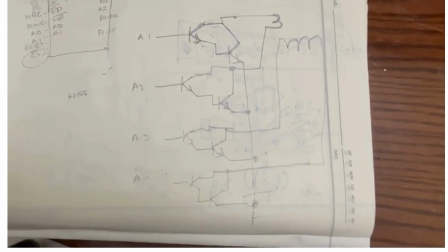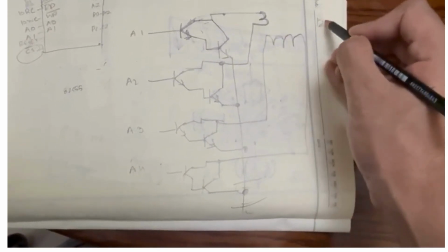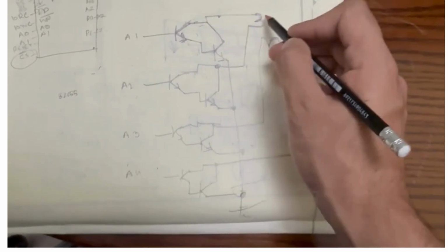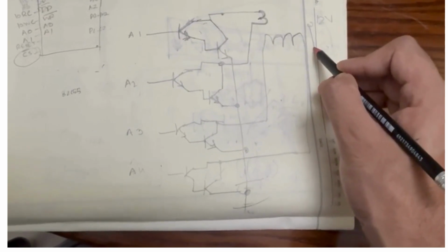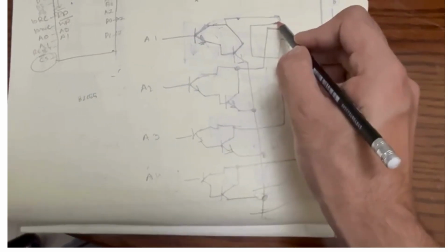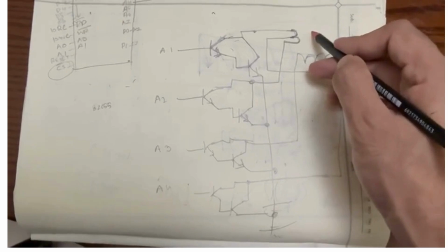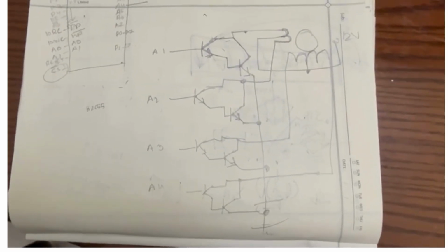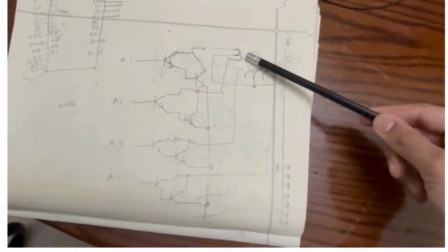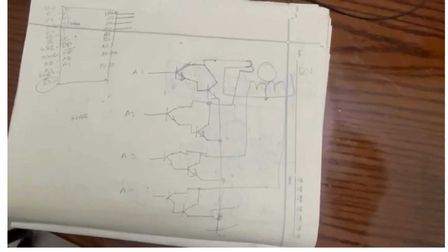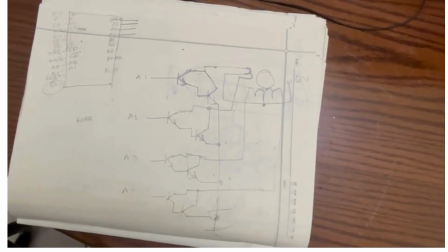So now this will be connected to the ground, and here a 12 voltage supply will be here. 12 voltage supply, and here's the circle. So this is the actual figure. So what is happening over here? Only two coils are being activated in a full step. I'm talking about full step. Just remember full step.